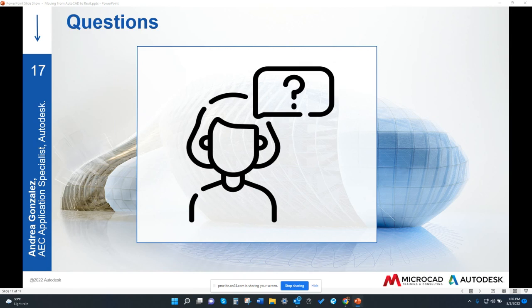For example, if you're working with a client that is not using an architectural model for doing his design, you can export your architectural background into Revit and use it for reference and add your discipline on it. So they are complementary. And as I told you, you also can take your details from there and convert them into Revit files. So there is some interoperability between both.